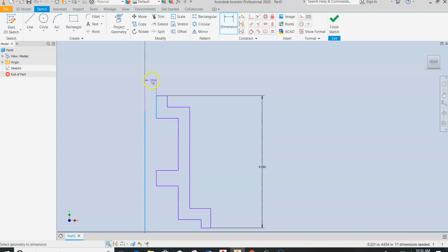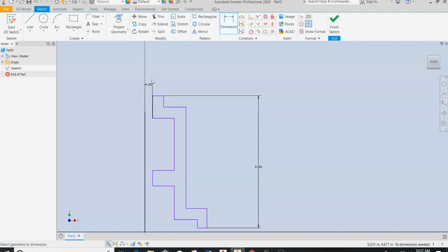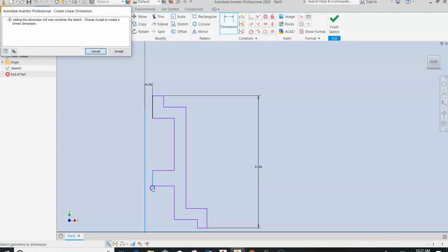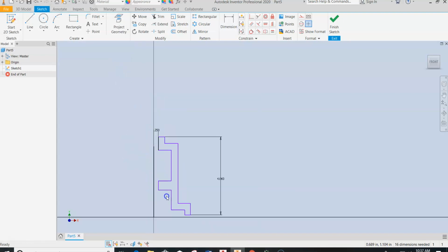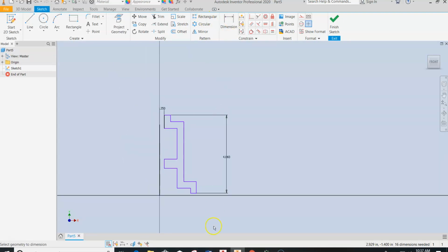So this one right here is the cutout. That radius is half of the diameter. The diameter is 0.5, so you can simply type in 0.5 divided by 2, and it's going to adjust that dimension. So that one is the same, and I think I've got that one constrained when I was making my sketch. Now I'm going to start to the outside with the largest diameter. The largest diameter is 3 inches, so I'm going to put 3 inches divided by 2, and there we go.